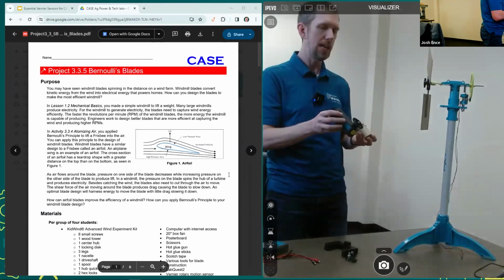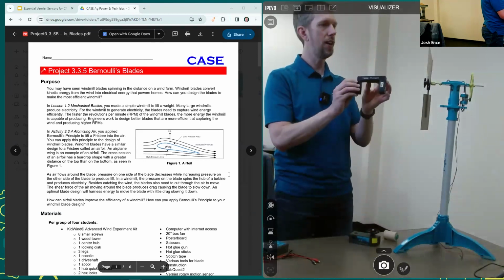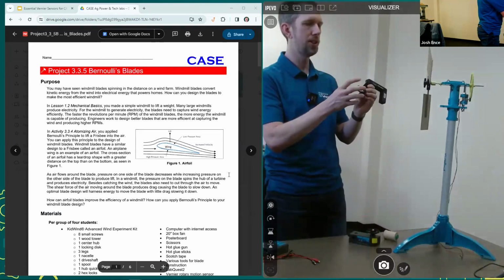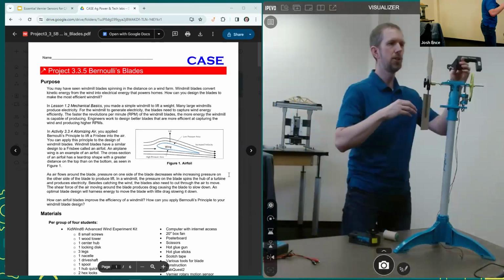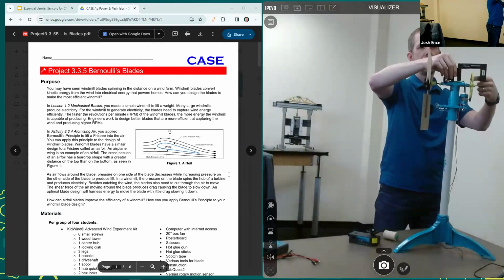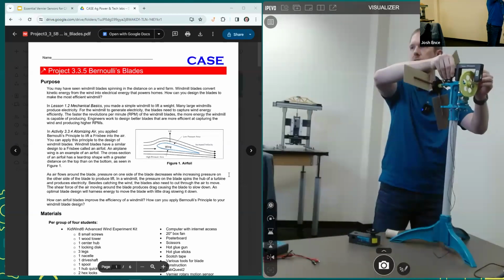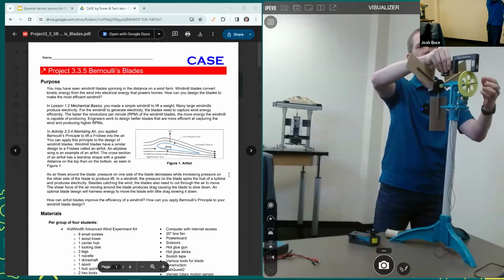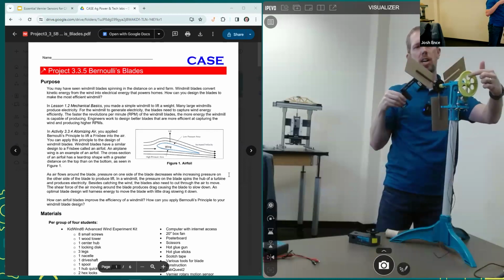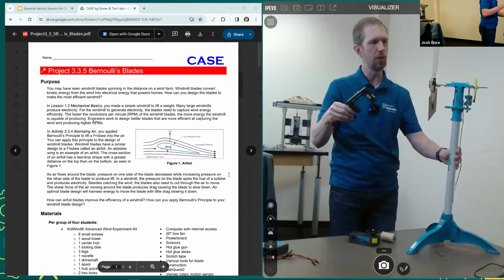You can also use this PhotoGate. It's actually a LabQuest PhotoGate, and we have a special mount. It's just a photogate bracket that mounts to the turbine itself in such a way that it measures this large gear here. As the turbine blades turn, the gear turns, and the photogate beam is blocked and unblocked as the gear turns. That's another great way to measure rotational speed.